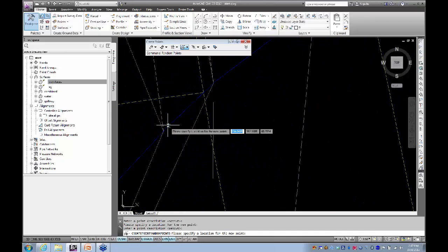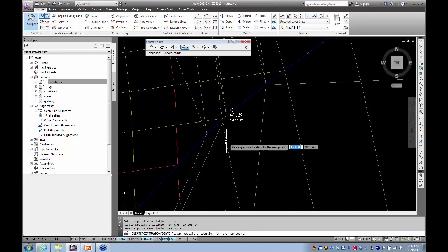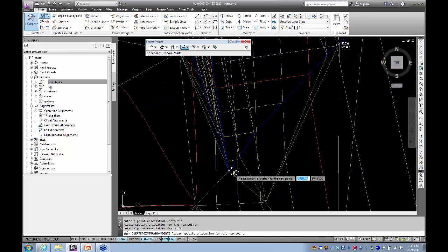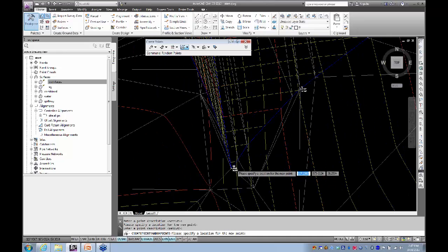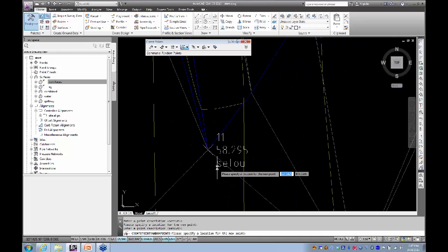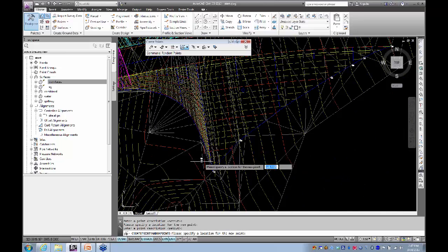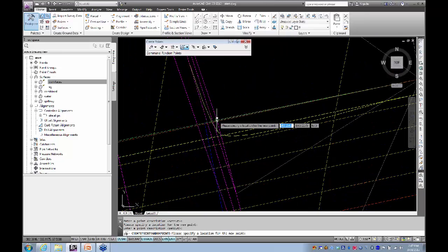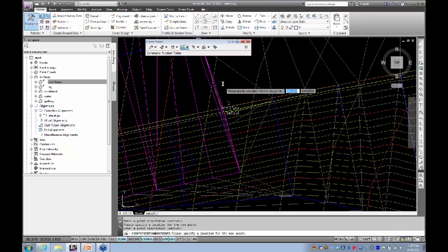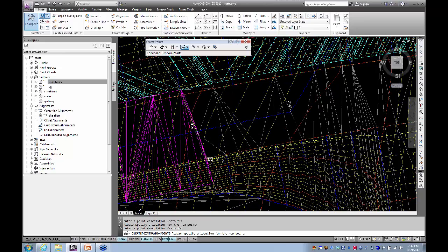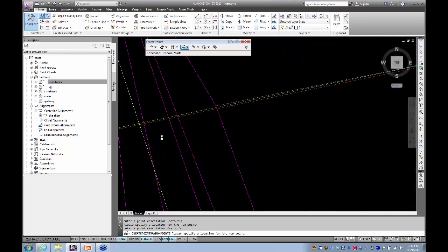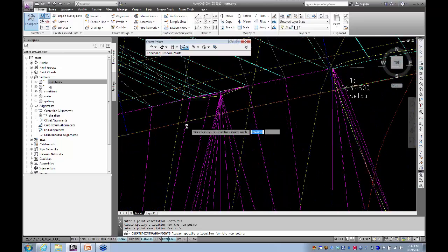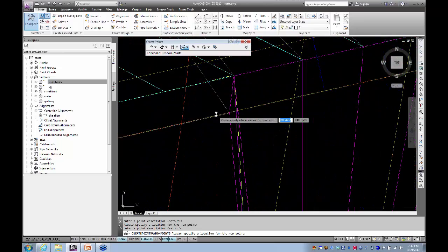Any points of interest, so changing in gradation there. Maybe this tip down here I want to point. You can see it's just grabbing the elevations of that surface, and that's where it's putting the point. And it's still using that set out description. I'm just hitting enter to accept that. I can pop one here, for instance, and we're getting the crest of the spillway. And there as well. Etc., etc.